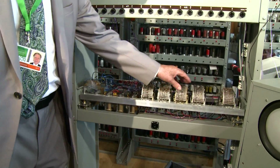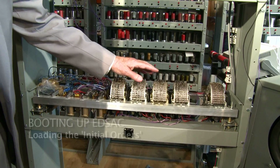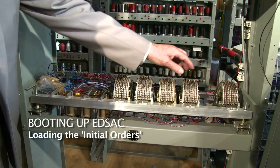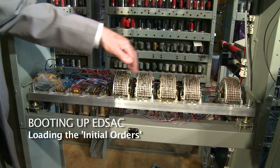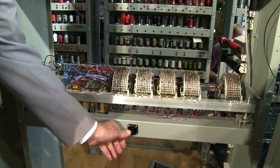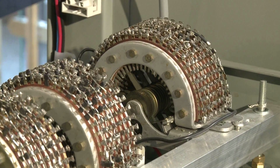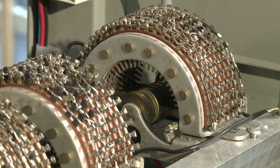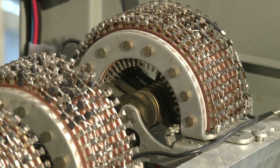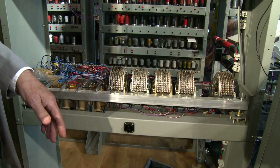These are standard post office unit selectors, and these four contain the data wired on the pins. The end one controls the operation of these four. When we want to start the machine, we simply push the button, one button, and these rotate round and sequentially put streams of data into the computer. At the end, the computer is now running and ready to accept paper tape.